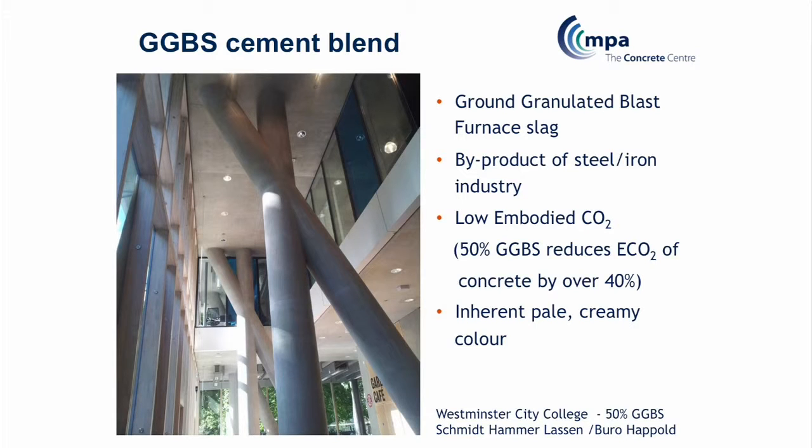So that's certainly a useful thing to think about. Also, there are other benefits. It actually makes the concrete inherently pale and creamy, so you get a much lighter concrete. So if that's used on the inside of a building, where you would be putting your concrete to improve the thermal mass, you can also improve the light reflectancy of the internal space as well, which is a useful thing to think about. It's part of your overall design.